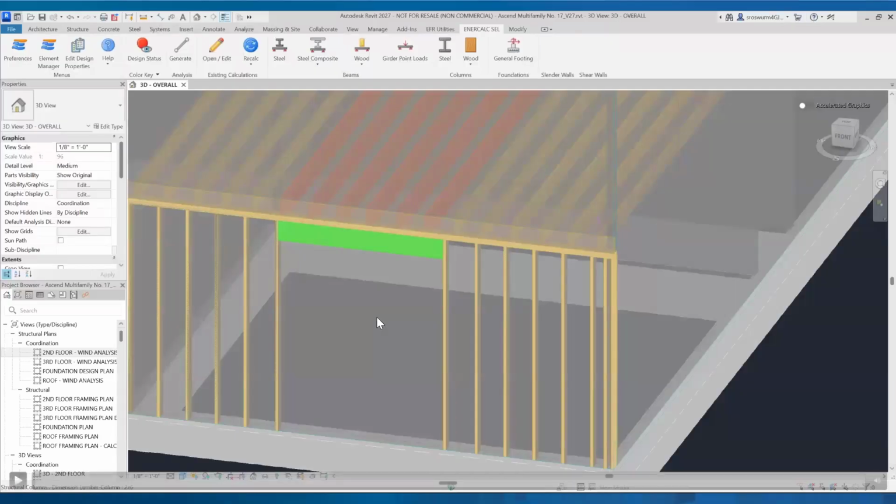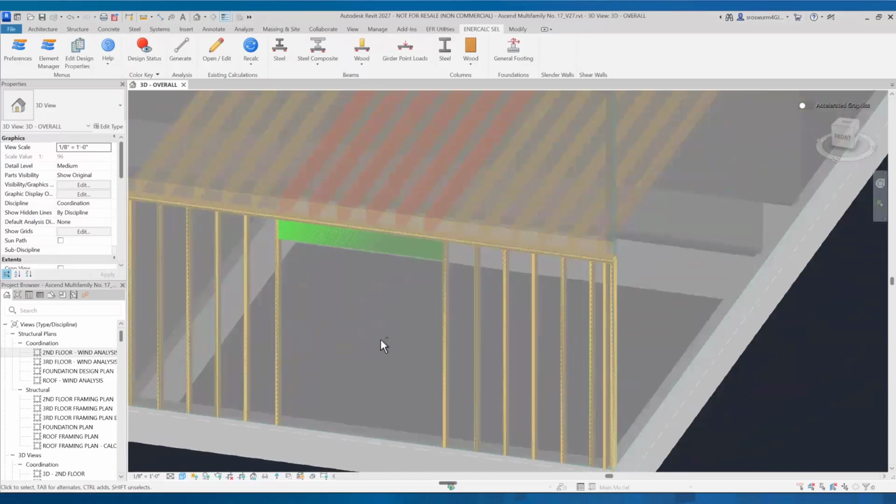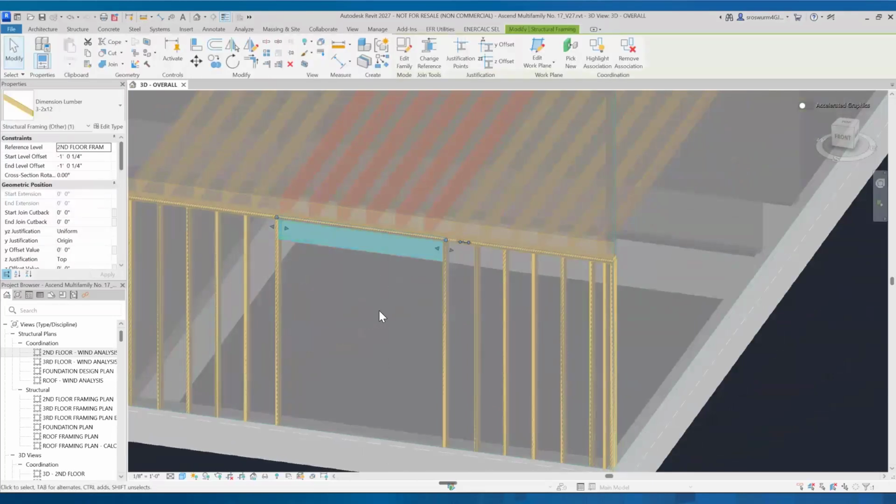Since we have done a header design already here, I went ahead and preliminarily sized some joists. I threw those joist reactions on a header. This header now has end reactions similar to the force transfer conditions we looked at a moment ago. That's going to allow me to go directly into sizing one of our studs at the end of this header. And we can launch that using an ENERCALC wood column launch, just like we did a second ago.